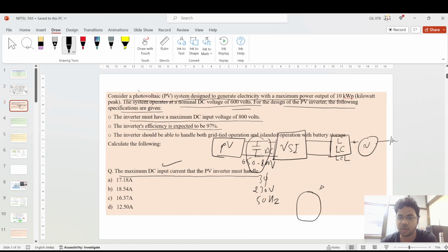After that you have the three-phase synchronized voltage source which is generated. The voltage at the VG terminal, the grid side terminal, is taken into account with the PLL to generate a synchronized voltage angle, theta. Then it is used for controlling the input side current generated by the VSI. This is done in the DQ frame.